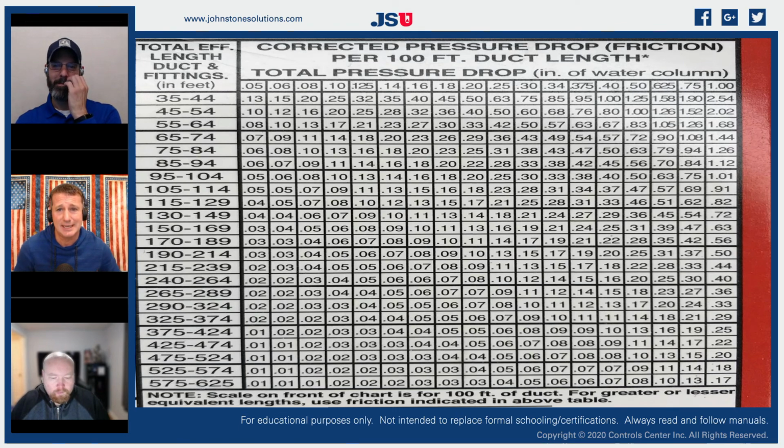What this chart is actually saying is that if we're calculating for 100 foot of duct length, and then we're going to start adding all of our fittings and elbows into that, it can change the amount of pressure drop. So as we start adding all of our links together, we have a calculation that needs to be changed. Because if I have a duct system that has all boots that are coming out of the bottom of it, it's probably not going to affect my total pressure. But if every boot in my installation is a 90, and we're trying to keep those tucked up into the floor joists really well, it adds a lot of restriction to my total system.